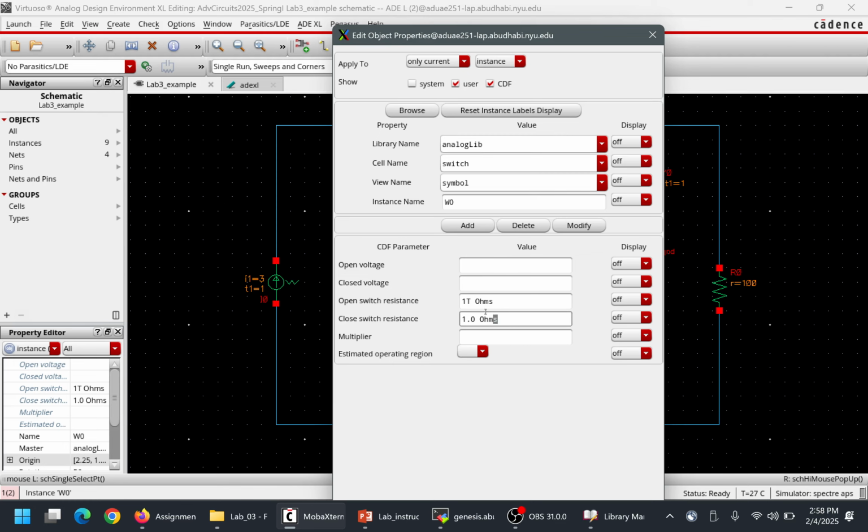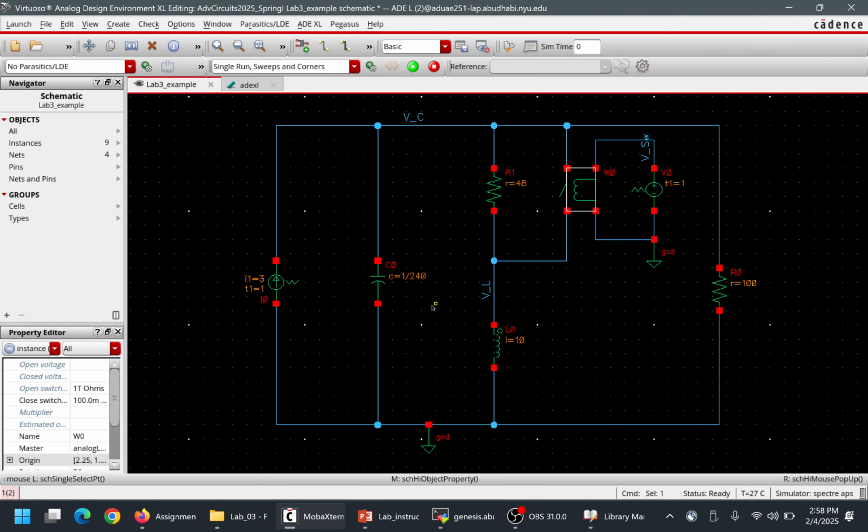The switch now has, when the switch is closed, a resistance of 1 ohm, which is quite a lot. You can turn the value lower, it just takes more calculation and the system sometimes crashes, but it's okay. We can choose 0.1 ohm. That's still okay. Because of the switch turning on and the components' internal resistances, if we choose a very low value instead of a substantial value, it's okay. Overall, the plot doesn't have a big difference. It has a very minute milliamps difference, which is not a big deal.